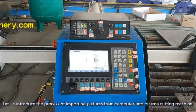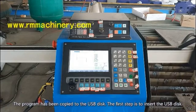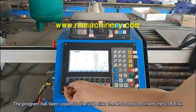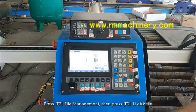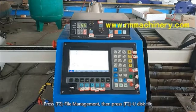Let's introduce the process of importing pictures from the computer into the plasma cutting machine. The program has been copied to the USB disk. The first step is to insert the USB disk. Press F2 File Management, then press F2 U-Disk File.